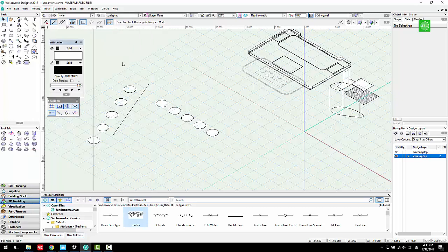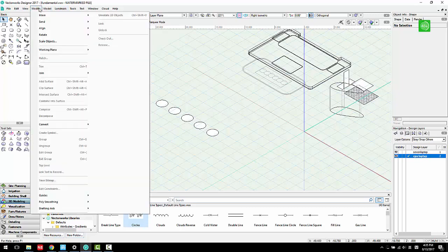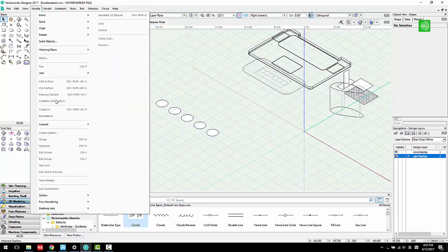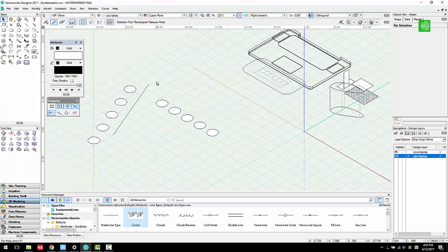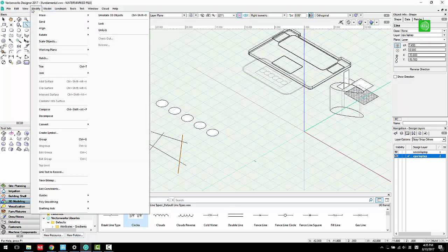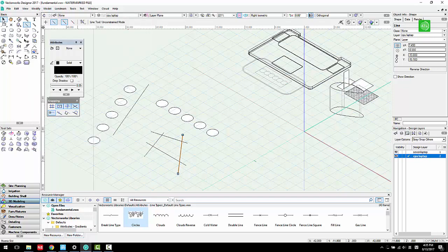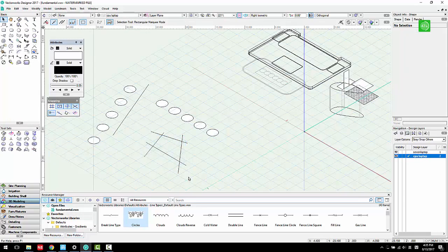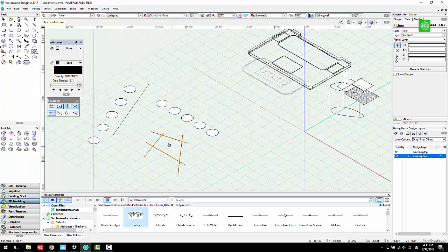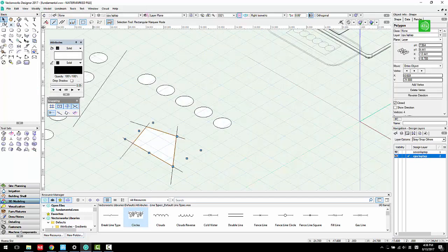And then the other thing is modify. Edits, I think the only thing you need to remember is duplicate and then modify. There are a lot of options in here. I'll just tell you some really important ones. For example, you draw a bunch of lines, right? And you could modify. If you select all of the lines, you can add surface, clip surface, intersect surface, right? You can combine into surface. Let's say combine into surface. You click it here, they turn into a surface for you.